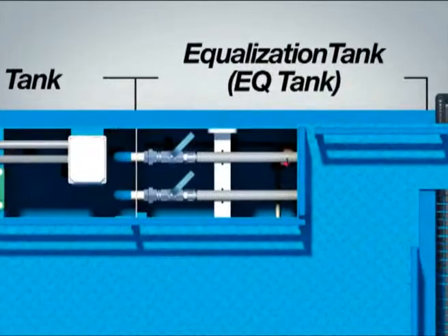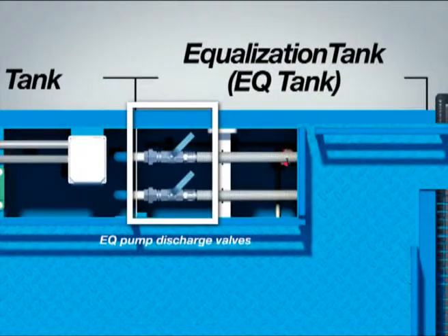The transfer pump discharge valves are usually set at 30%. Please flush them at least once a day. This can be done by opening the valves 100% and switching the pumps to hand mode at the control panel. Observe for 2 minutes and make sure there is nothing clogging the pump.